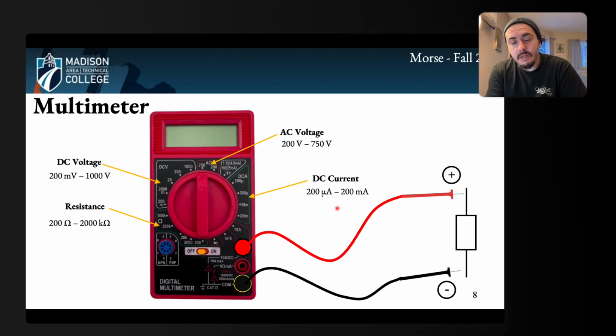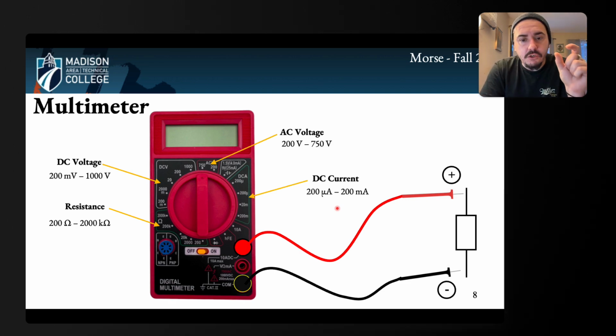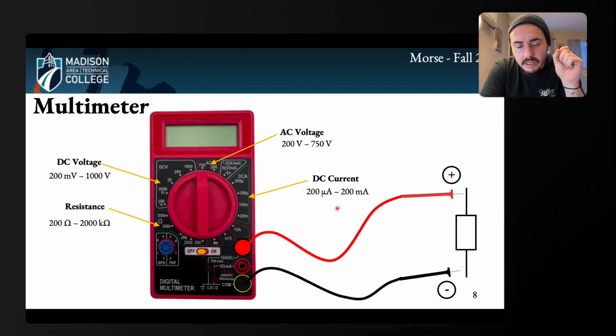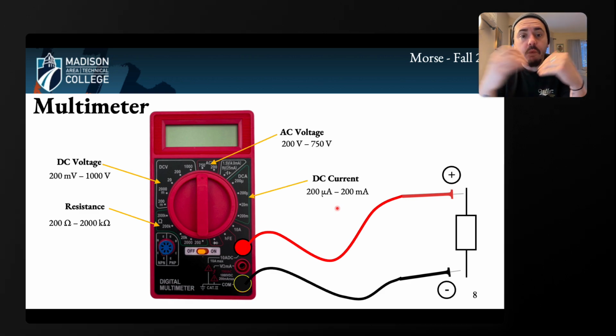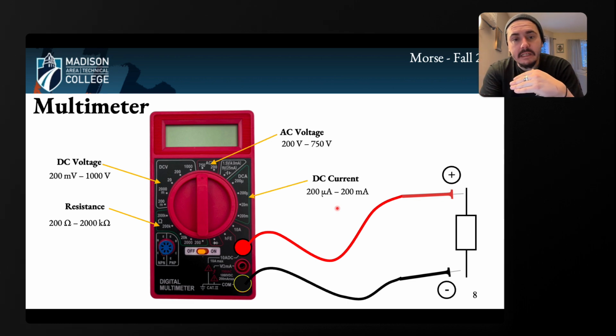If it's being provided 20 milliamps, it's at a total on state. Or if I have a measuring device, a sensor, and I measure the current from it, and I measure 4 milliamps, that's typically the lowest. So that's the zero, or whatever the bottom measurement of that device is, and then 20 milliamps would be the maximum measurement that the device can make.